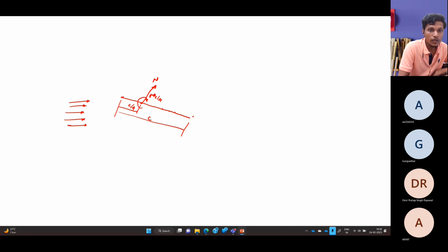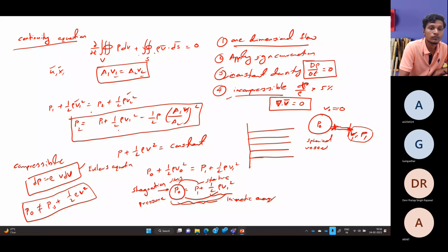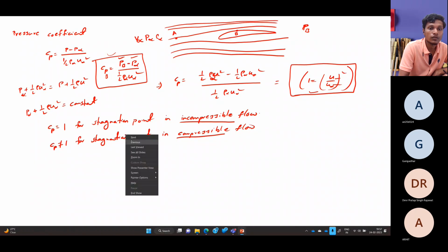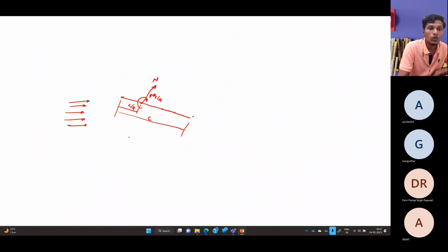Now if I want to find what is the moment at the leading edge, there are no other external forces, but I want to find how much moment is acting with respect to the leading edge. Moment at the leading edge is just equal to the moment at the quarter chord point. The same moment will act there, plus you see this is creating one more clockwise moment.